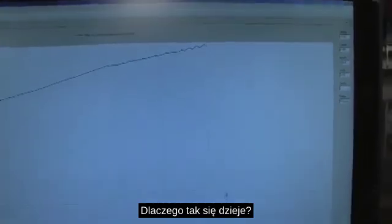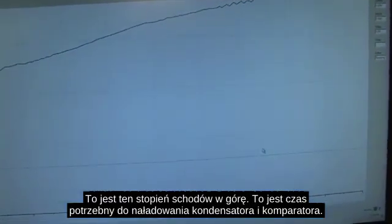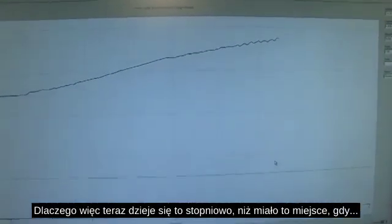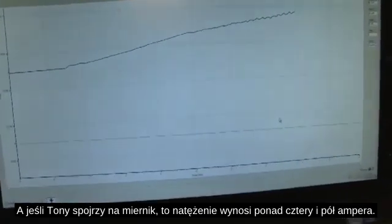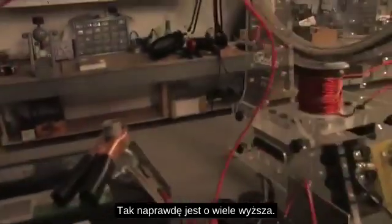So why is that happening? That's the stair step up. That's the time that it takes to charge the capacitor and the comparator. So why is it stair-stepping more now than it was before? Because I changed the timing to like once a second, see it? Oh, okay. And it's over 4.5 amps. If Tony looks at the meter, actually, it's a lot higher than that.